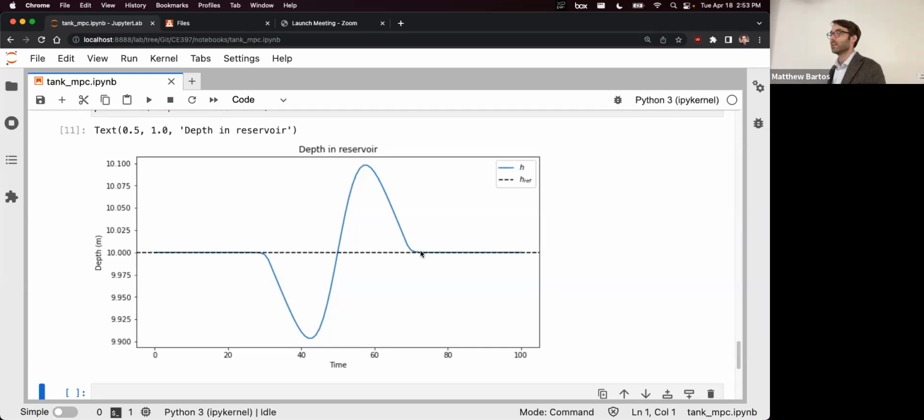It also helps deal with the nonlinearity of the system. If you have a nonlinear system, the system will change depending on your control input. So if you optimize over these moving horizons, it deals with that nonlinearity by essentially breaking it up into smaller chunks and linearizing around each time window. Okay, so just keep that in mind. That's typically how MPC is implemented, as a windowed process that moves forward in time. Okay, are there any questions on MPC?